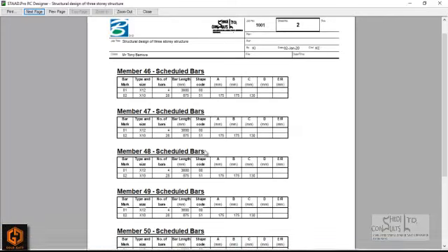So STAAD tells you need 4 of those bars, so 4 number of 12 mm reinforcements, shape code 00. If you look at 01, it gives you the total length, which is 3.6. For 02, it tells you the individual length of the bar, so 3.6 is the length of one of the bars. Now, for the 10 mm bar, which is the stirrup, it says you need 28 numbers of the stirrup.